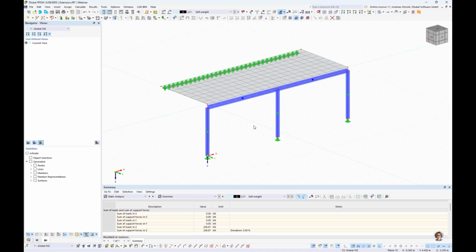And a surface with the load transfer stiffness type has no structural effect. That's really important, and you can use it to consider the loads from surfaces that have not been modeled. For example, as I said, facades, structures, glass surfaces, trapezoidal roof sections, and so on.